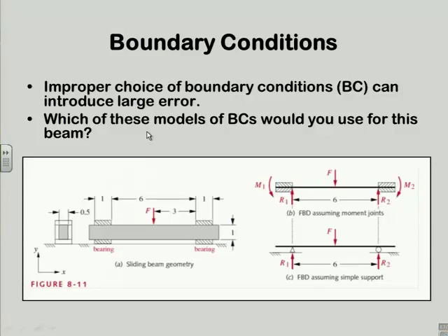At the other extreme, it's simple supported, as if this thing had no length at all. It's just sitting like there or someplace. And that's the classical way you'd describe that, with a pointy thing on one end and a round thing on the other, so if it stretches due to thermal expansion, I don't do anything bad to it. It can roll on the roller, yeah? So here's simple support. There's cantilever type support, or fixed. And the question is, which of those is more appropriate, or is either appropriate?